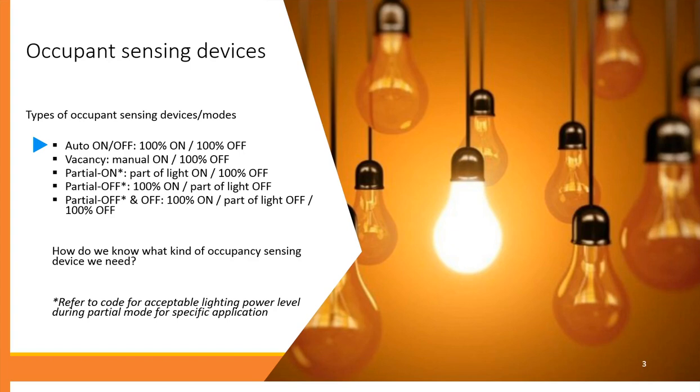Now, the occupancy time delay per code, you're allowed up to 20 minutes. Most manufacturers will produce their products with the default standard time of anywhere between 5 to 10 minutes, which is very common, very standard, still effective. You don't actually need to go all the way up to 20 minutes for the time delay.